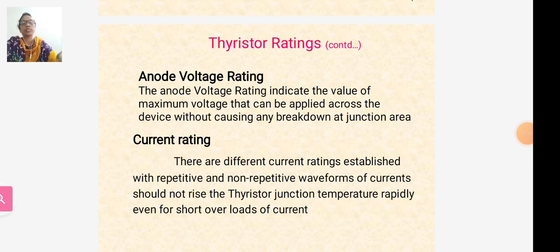It is the maximum reverse voltage that may occur repeatedly in the reverse direction at the allowable maximum temperature that can be withstood by the thyristor without breakdown. Next is the peak surge reverse voltage. It is the maximum transient reverse voltage which can be safely blocked by the thyristor. Its value is about 130% of VRRM, the peak repetitive reverse voltage.